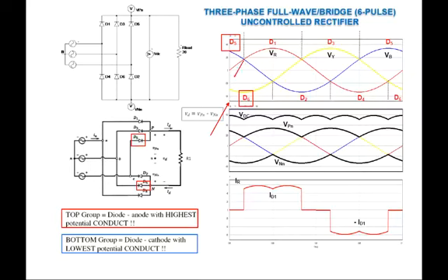Okay, so now as we start to move away from the 0 degree, right at that 30 degree, whereby we have the intersection between blue phase voltage and red phase voltage, just across that, now the red voltage is the highest compared to the 3 voltages. Therefore, the diode will switch from D5 to D1.